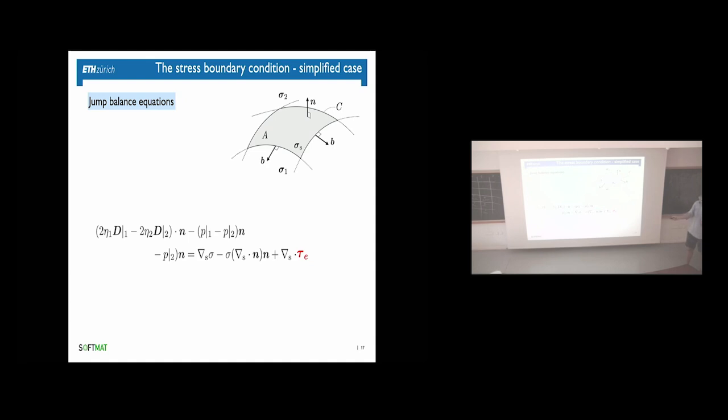This one, which looks the most complicated, is actually the one that you know best. N is the unit vector, nabla S is the surface Laplacian, and this dictates curvature, right? So this is a complicated way of writing curvature, tensorial. And so this is the Laplace contribution, capillarity. This is gradients in surface tension. We'll see what this means. Gibbs and Marangoni stresses. And then this is truly interfacial rheology.